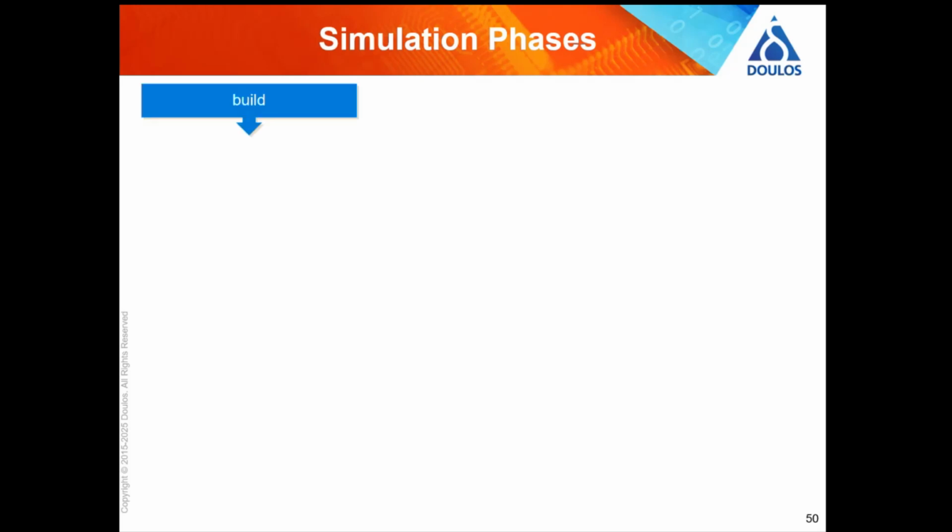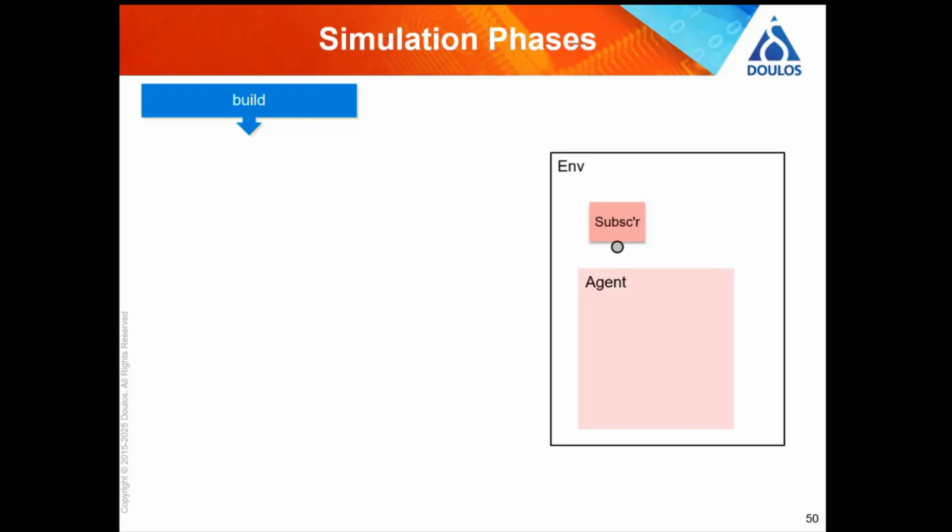And also in UVM, there is a time dimension. There's a time element. Because we're making our test bench out of classes, at time 0, nothing exists. In VHDL, once you've compiled your code, everything exists. Whereas in UVM, all of these pieces of our test bench are now made out of classes. So the first thing we have to do is create them, what's called construct them in object-oriented design. So we create our test bench, and of course that needs to be the first thing we do.